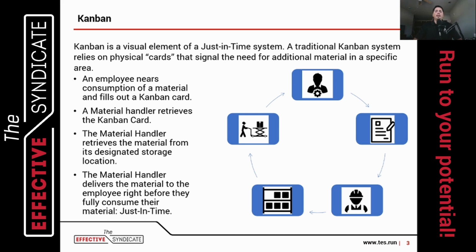I remember at Toyota, it was pretty amazing. On the line, you might be running out of parts and you're looking at it and you're like, man, that's really close to running out. Almost every single time you turn around and there's the material handler right before you're about ready to run out, bringing more. And that's how the process should work. You shouldn't have a whole lot of it in one location. It should be brought to you as you need it.